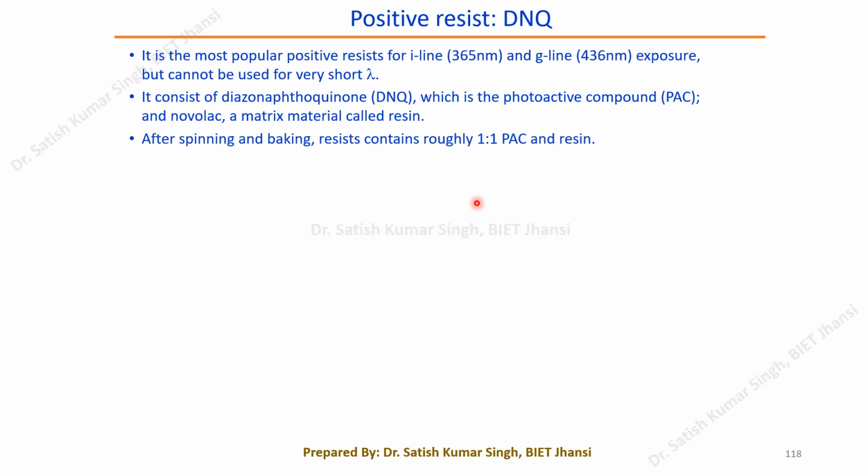We bake the wafer after coating the positive photoresist, before the exposure. We have not done any exposure, but we have to do the pre-baking. All the remaining solvents are removed by the spinning, and those left on the wafer surface can be removed by the pre-baking, before going for the exposure.